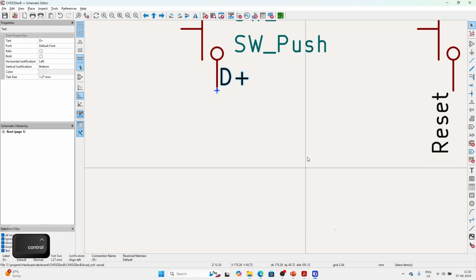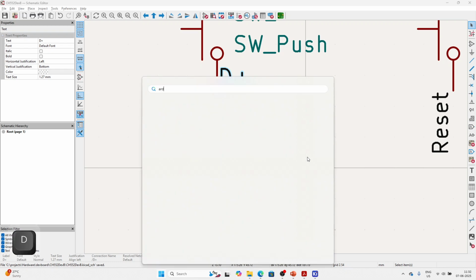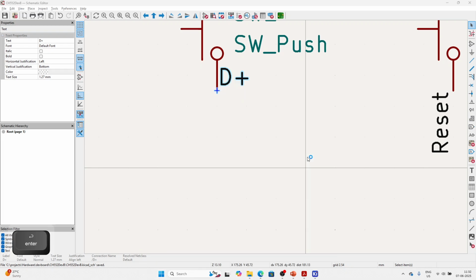Going a bit off recording here, because most of you would be using the Arduino IDE. There is already a library for this CH552 to program on Arduino, which uses this particular pin 3.6 itself and not 3.7 as the communication pin.